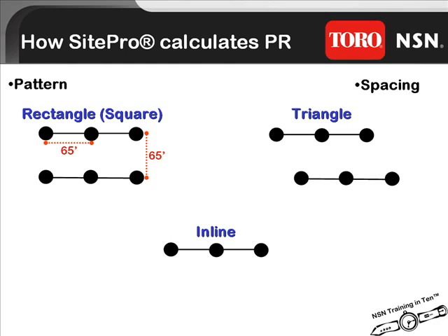With a 65-foot head spacing, the row cannot be placed at 65 feet as well, because this would create a head-to-head distance that is greater than the head spacing, and the goal of 100% coverage would be lost. So there's a formula that's used when designing triangular coverage that squeezes the row so that the row spacing is consistent with the head spacing, thus providing 100% coverage.